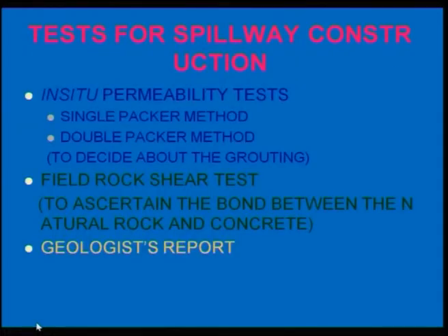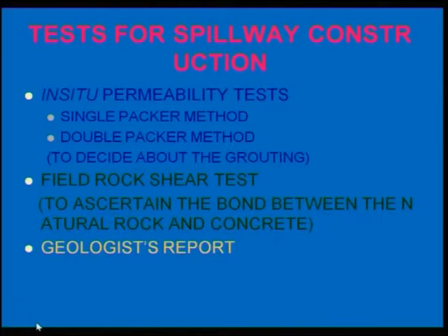So, tests for spillway construction, like for irrigation projects, you can do, because this is a continuous flow of water in the soil. The in situ permeability test you will have to determine, because it is related to permeability, which is what I am discussing. By means of the single packer method or double packer method, to decide about grouting, then the field rock shear test, and also some geological report you need.